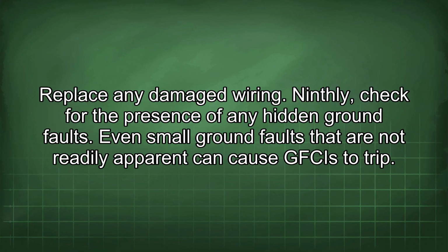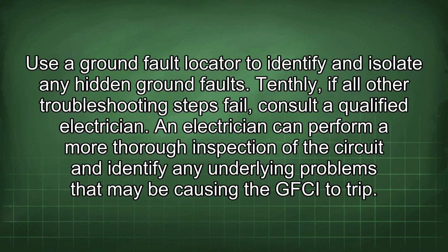Ninthly, check for the presence of any hidden ground faults. Even small ground faults that are not readily apparent can cause GFCIs to trip. Use a ground fault locator to identify and isolate any hidden ground faults.